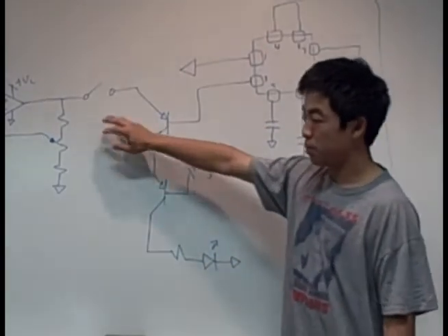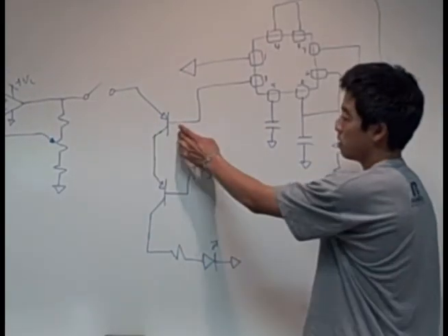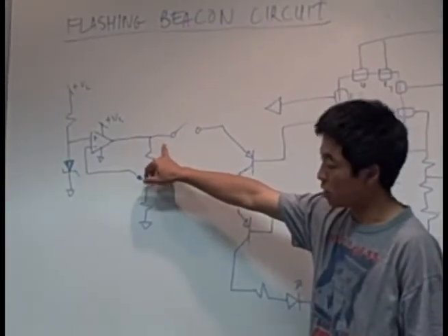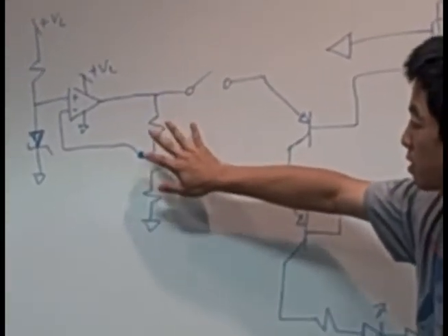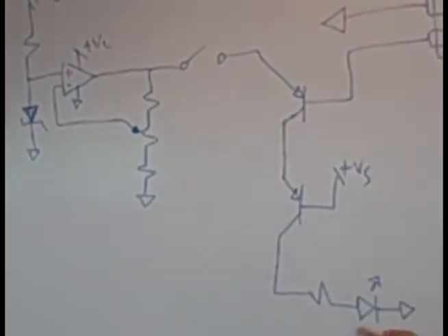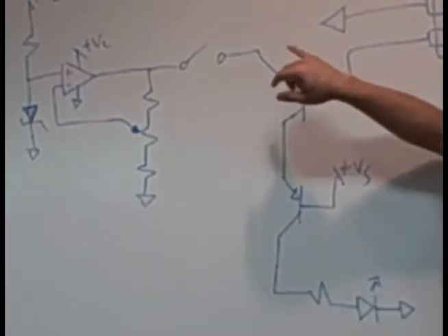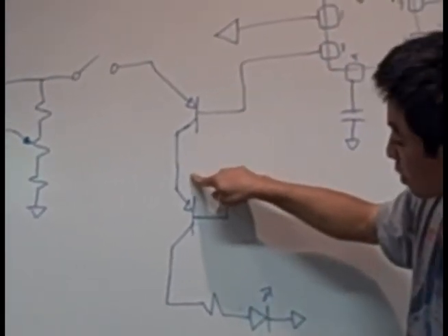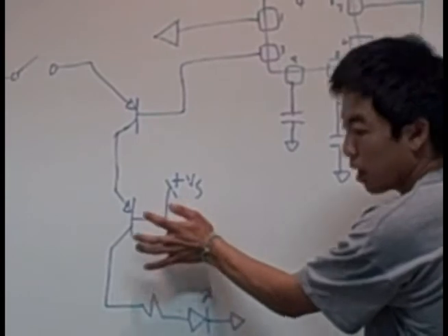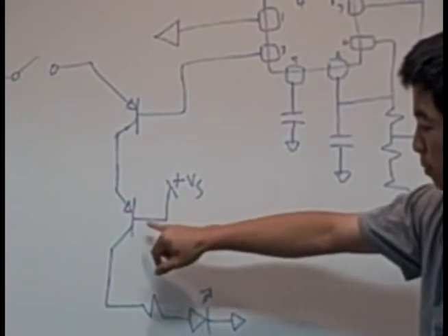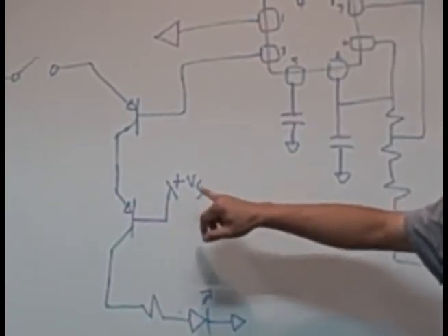And so, similar to the illumination circuit, the emitter of this PNP transistor is supplied with a constant voltage and current from this current amplifier. This current amplifier can be adjusted by the potentiometer right here, which later on affects the intensity output of the LED. And so when this transistor is on and this is outputting a low, the voltage and current is allowed to flow to this PNP transistor, which again, similar to the illumination circuit, the base is supplied from the voltage of the solar panel.